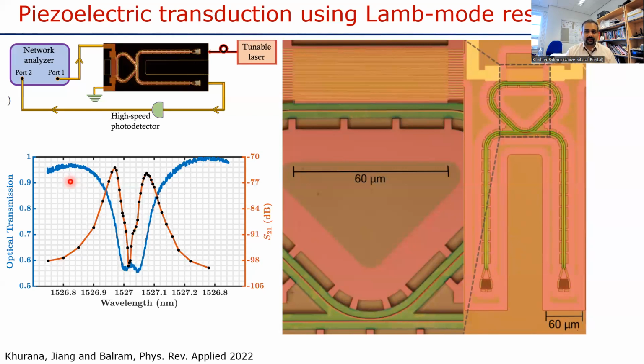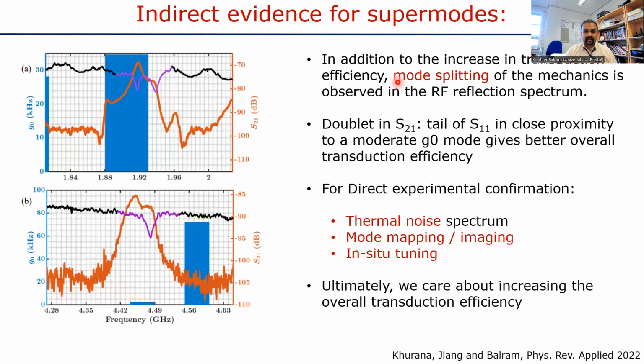And so how do these structures look in practice? Well, these are representative images. You have grating couplers to couple light into these photonic integrated circuits. You have suspended optical micro-ring resonators in which the acousto-optic interaction is being engineered. And the key here is that one arm of this micro-ring resonator is being modulated by this contour mode resonator that's located adjacent to it. We are looking for a mode hybridization between the breathing mode of this rib waveguide and the resonant mode of this contour mode resonator. And so we achieved that.